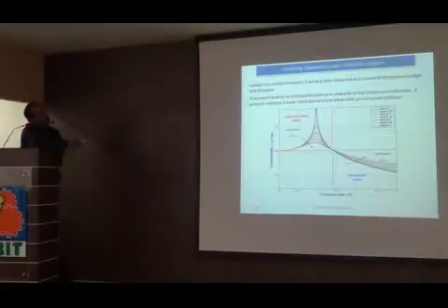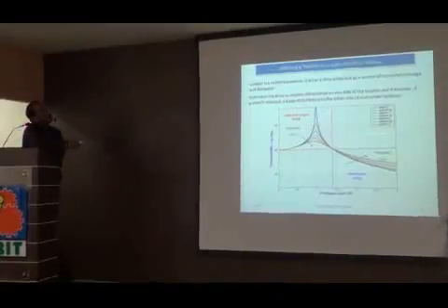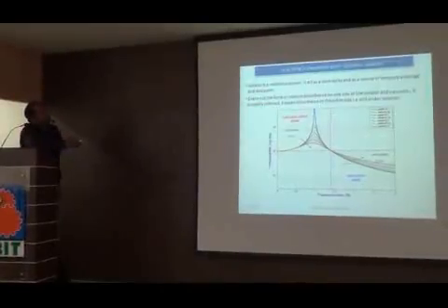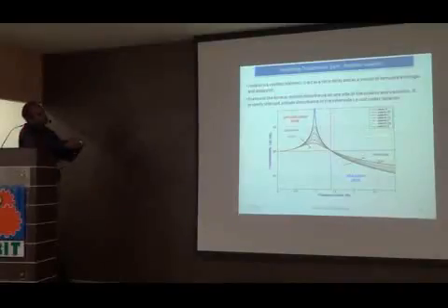Isolator, as I said, is some kind of resilient element. It is in between the input and the system. What it does is it acts as a time delay. It takes the energy and releases it very slowly, as a source of temporary storage, and dissipates it. Some energy is dissipated in the form of heat. So one should be careful that the heat generated in the isolator does not cause damage to the isolator.